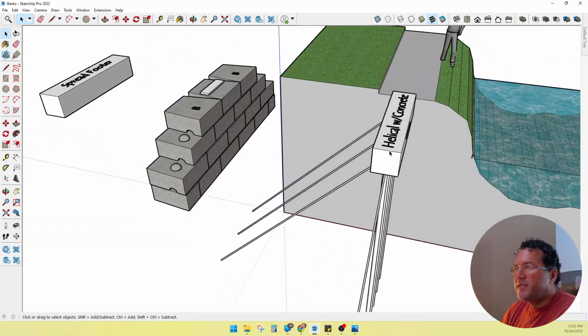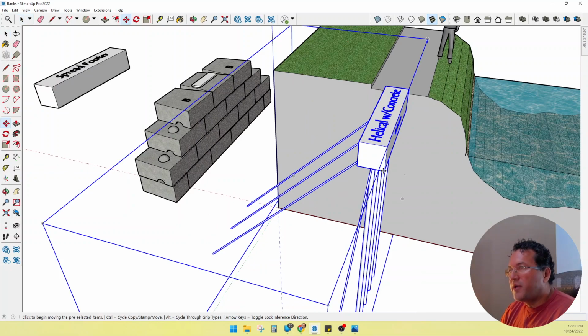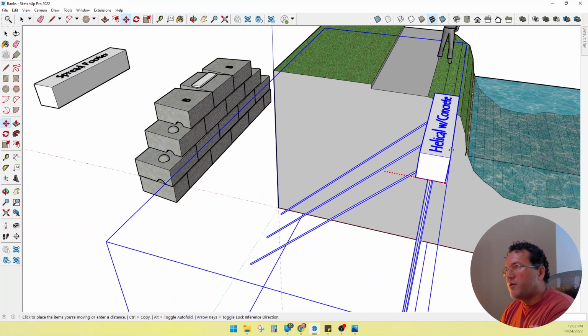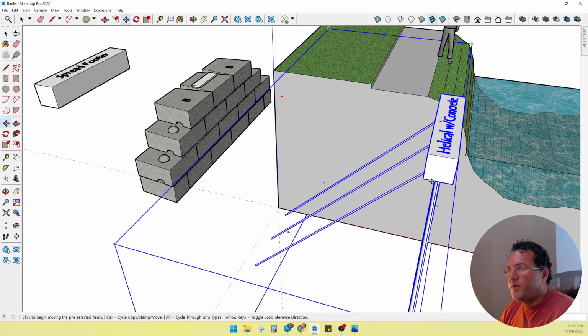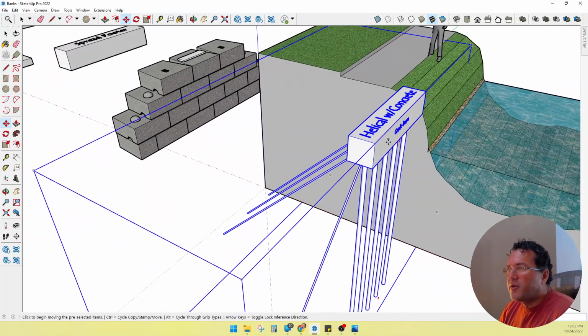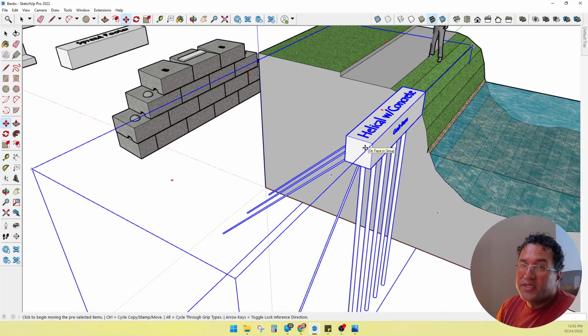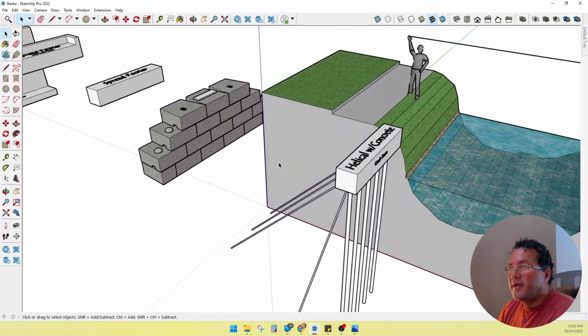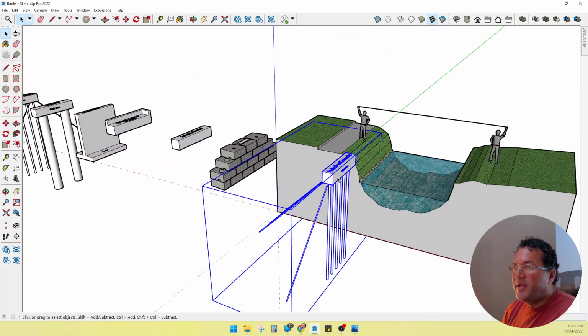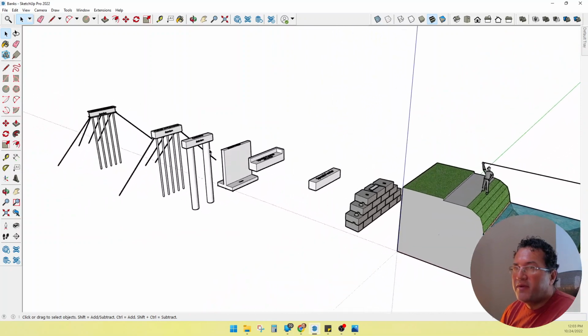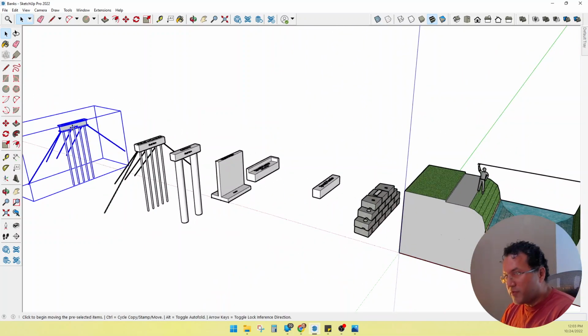Now, sometimes we get so close to the waterway, we're kissing the waterway. We're so close that there's not even enough room to pour concrete, or for whatever reason we can't get close enough to pour concrete, or the job site's so far and remote that we can't even get a concrete truck up there. It's too rough and rugged of an area where getting a concrete truck is just not possible. So in that case, we will just do a steel grade beam instead of a concrete grade beam, and that's the very last one over here. We use a steel grade beam.